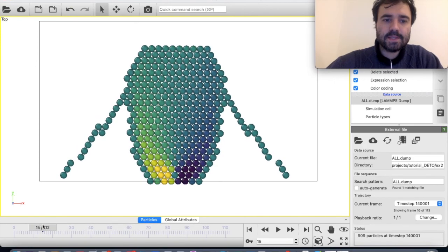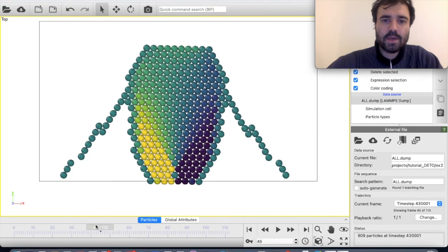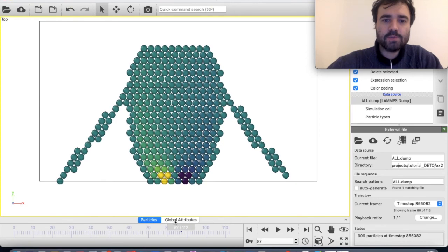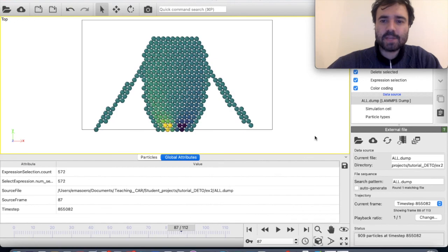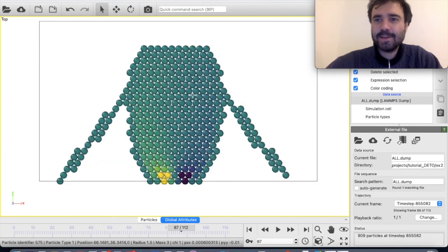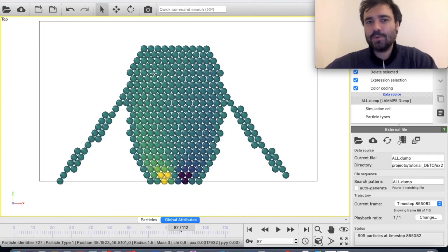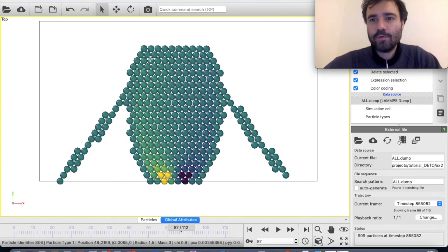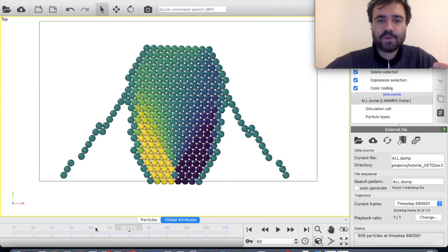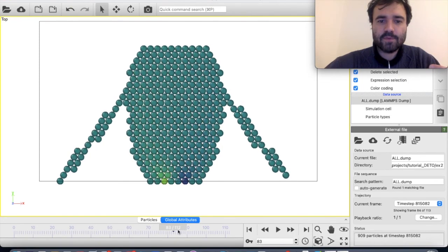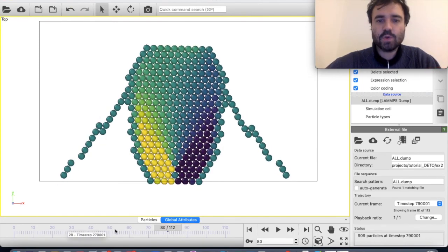And you see that indeed, probably a second step started because it went up to this point and then it went back. And when it goes back, it's because the system is actually now trying to optimize the structure given the new distribution of load that we gave to it. This is not the point of this exercise. We just wanted the first step, so up to here, before it jumps back, because this is what we can use to now draw using Excel the horizontal force displacement curve for this structure.